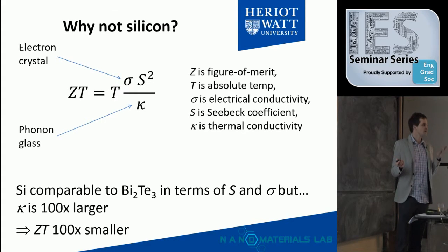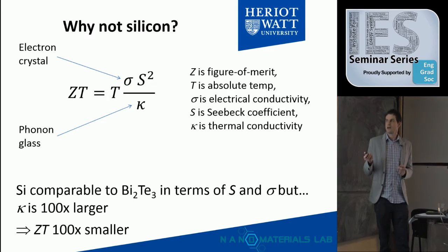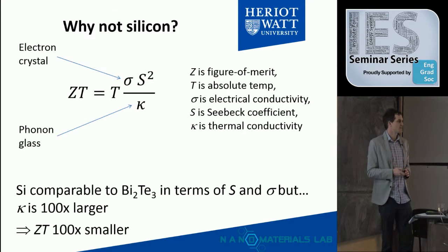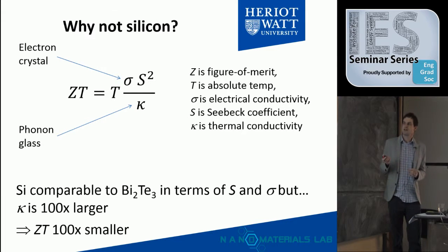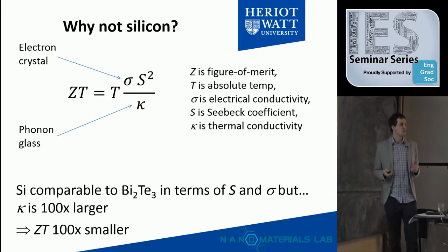But it's basically the higher the better, and it's determined by these material properties here. So we have the electrical conductivity of the material, its Seebeck coefficient squared, and divided by its thermal conductivity. So this is where the real challenge is with thermoelectrics. So you can see we need a good electrical conductor, a poor thermal conductor, which